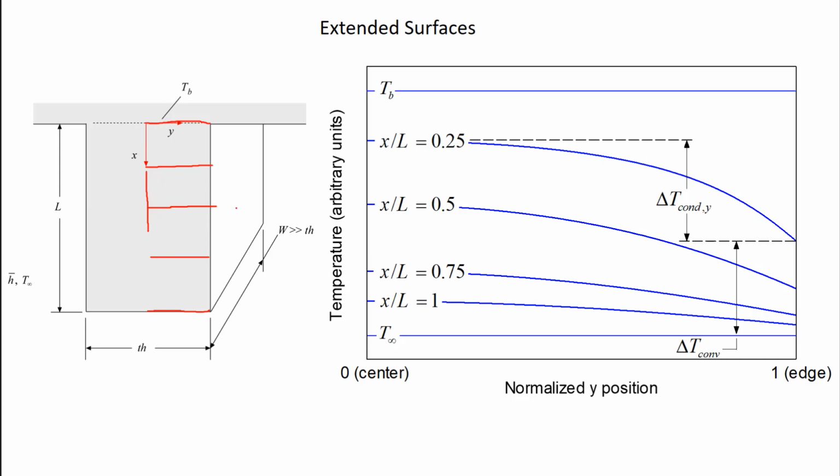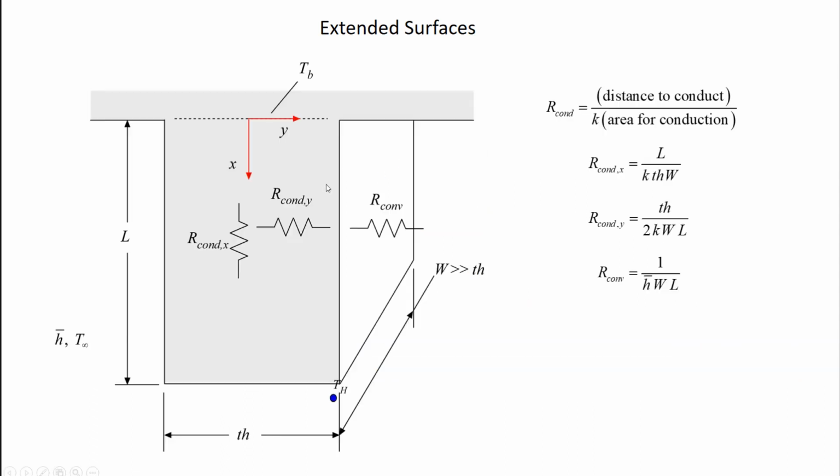And because it's a two-dimensional problem, we can't solve this problem using thermal resistances, right? All of our thermal resistance equations came from these one-dimensional solutions, but that doesn't mean that we can't use those thermal resistances to understand the problem, right? Because that's, as I've said several times, kind of our main tool for doing that. And the way you think about a problem like this is you have to realize that each of the heat transfer mechanisms comes with its own thermal resistance, right?